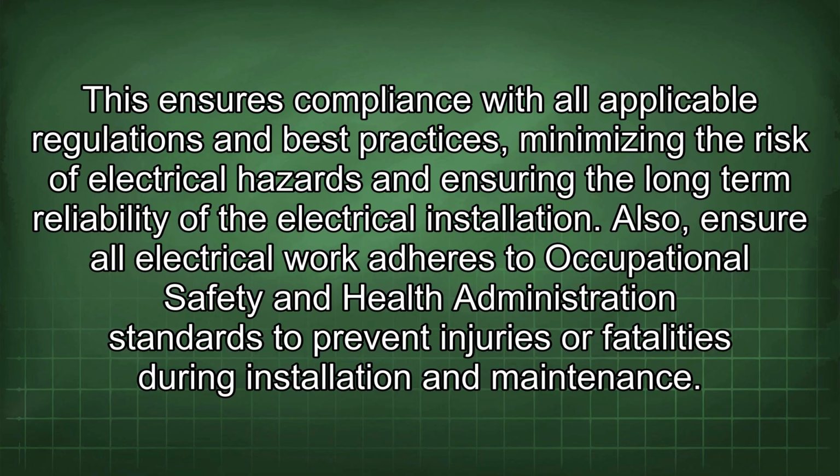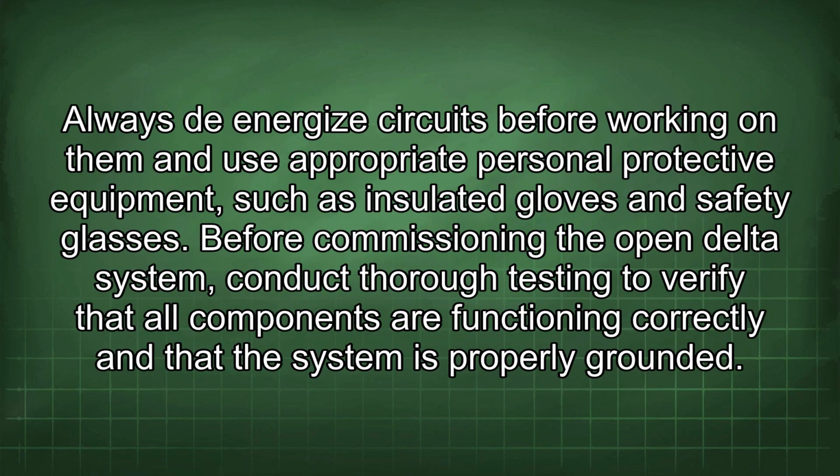Also, ensure all electrical work adheres to Occupational Safety and Health Administration standards to prevent injuries or fatalities during installation and maintenance. Always de-energize circuits before working on them and use appropriate personal protective equipment such as insulated gloves and safety glasses. Before commissioning the open delta system, conduct thorough testing to verify that all components are functioning correctly and that the system is properly grounded.